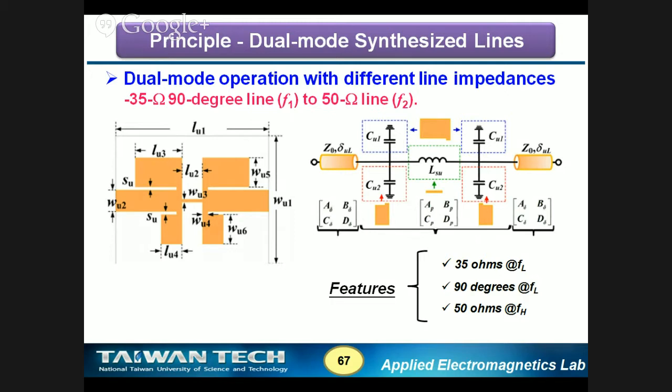Of course, not manually, but with a mathematical tool like Mathematica. Using it, you can derive the ideal values of your inductance, your capacitance, and the electrical length of the line. Then you substitute them back into ADS to verify your design concept.